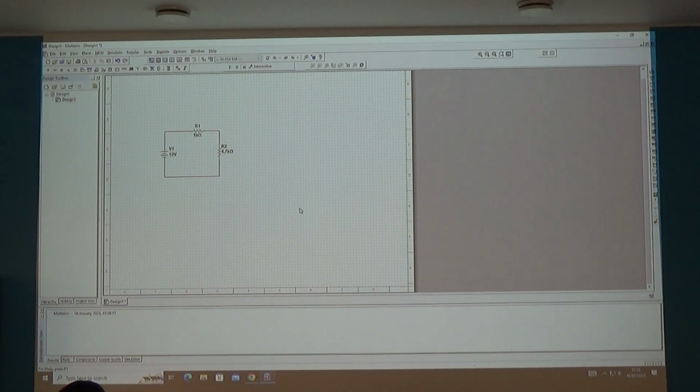That really is magic. Now the reason I tell you that is because we're going to do some measurements on here, so let's do that. So, what have I left off the circuit? The most important bit to make that work is the ground. Multisim does not understand circuits which are floating around in free space. And for all intents and purposes, I don't think physics understands things that are floating around in free space. It's a big problem to do with RF, but we don't need to go there yet. But Multisim must have a ground connection for it to simulate, so we need to place a ground.